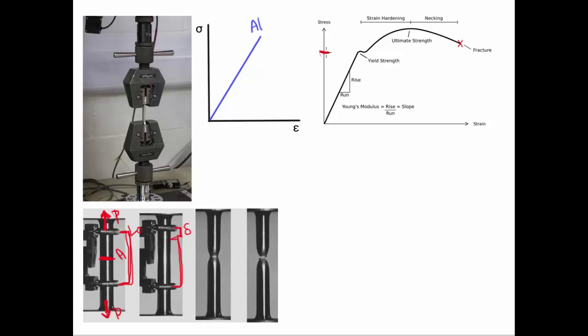That is, once we're above this line, if I double the stress, then the strain will not double. If I increase the stress 3%, the strain will not increase by 3%. It will increase by more than 3%, actually. At this point, small increases in stress result in larger strains than we are accustomed to seeing. The object really starts to pull apart.